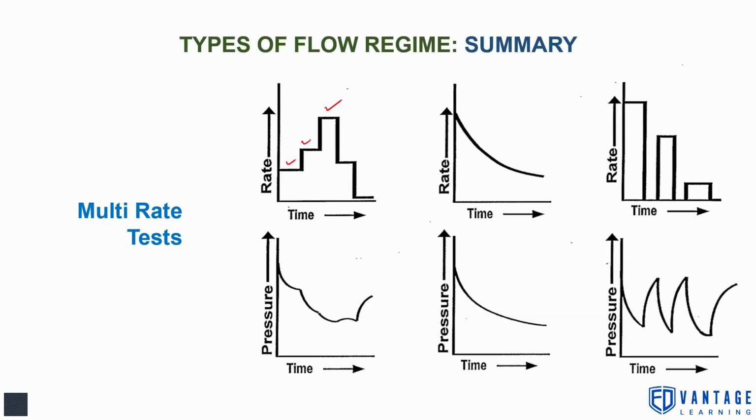So this is low beam, mid beam, and high beam. At high beam, the pressure drop is drastic as compared to the initial reservoir pressure. So that is how we see which choke is optimal for getting production from this well. That is very important. So multi-rate tests help us in that. We can understand which rate will give us the optimal flow production rate, the maximum production rate.